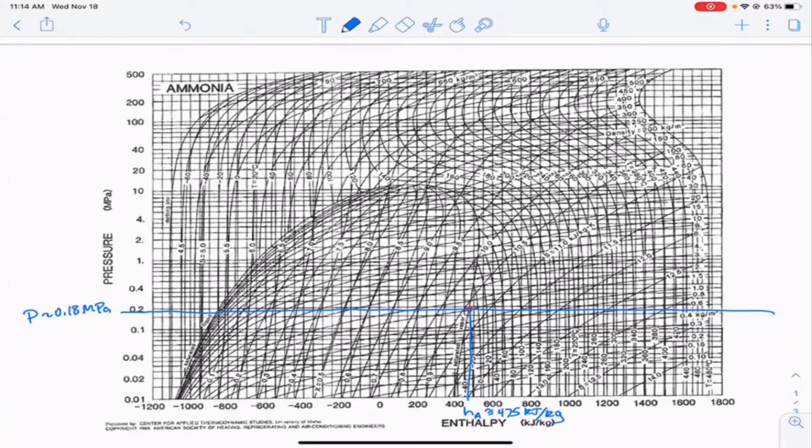One of the things that you'll notice about this diagram is that it's not very well broken up into segments, right? So, you could just as easily draw a straight line down and say, I think that's more like 470. One of the lessons here in refrigeration cycles is that even if your numbers are a little different, when we calculate things like the coefficient of performance, it'll be really similar. And it's something that we're just going to have to be reasonably comfortable with.